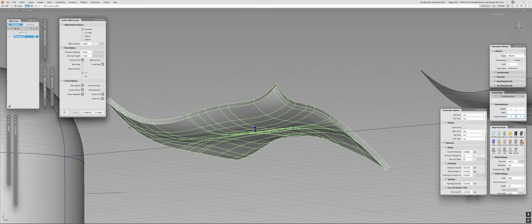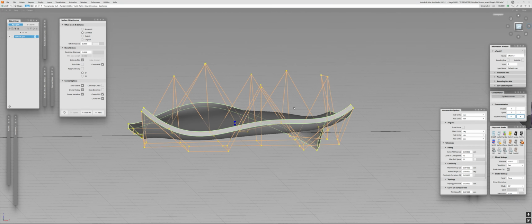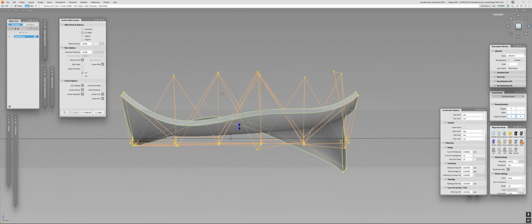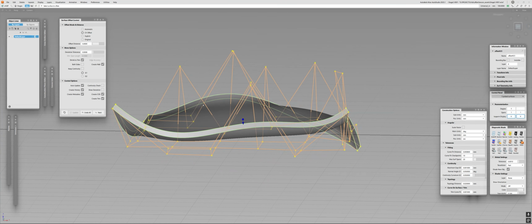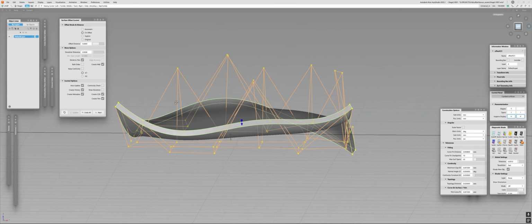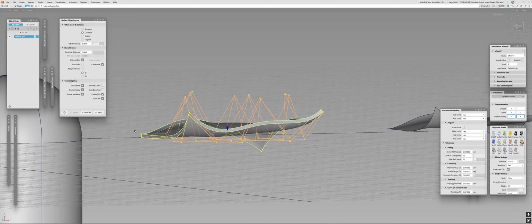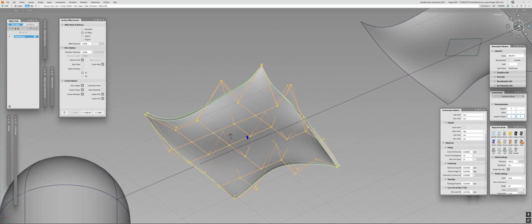Now, what are the other options here? Well, I can go in this time and use a CV offset. Why is it beneficial in this regard, instead of using automatic? From my explanation in Grasshopper, you already know what the CV offset does. It moves the CVs. In situations where the quality of the distance is not that important, and the surface is not periodic, using CV offset can be very beneficial because, first of all, it's very lightweight.